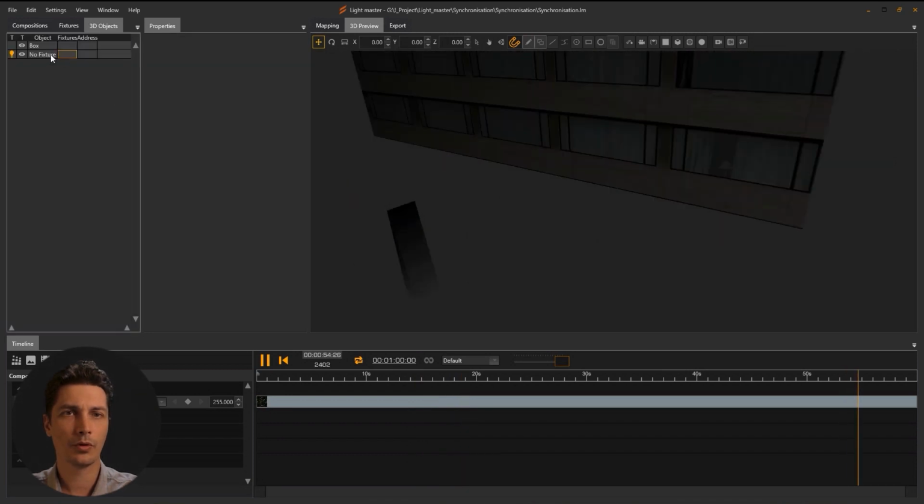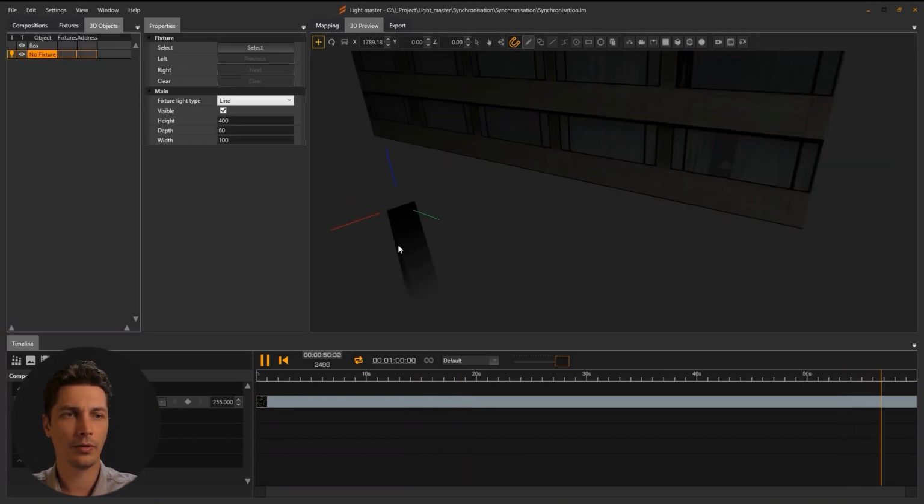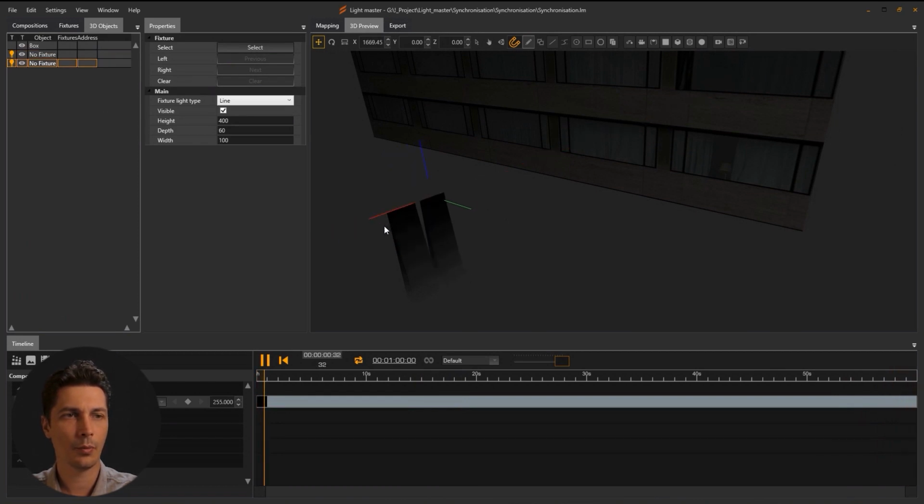You can go further in two ways. The first is to select the device, press Ctrl+C, Ctrl+V, duplicate it, relocate it to the preferred position, and repeat, and consequently obtain a series of illuminating fixtures. Not convenient if you have extended straight sections. Then you have the option to employ the clone tool for your convenience.